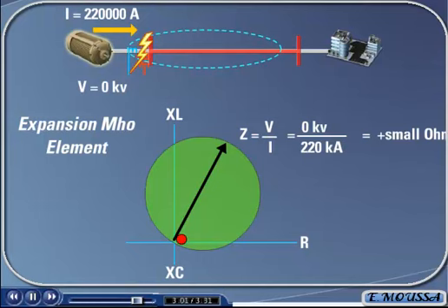To make sure that the Mho characteristic does realize this as being an internal fault that needs to be cleared, the relay recognizes the low impedance of the line, sees that the value is positive, and enlarges the radius of the circle. Since the Mho circle now extends past the origin to include a larger area, the location of the fault is sure to fit in the zone of protection. Therefore, the fault can be cleared properly. Notice, however, that the reach of the Mho circle did not change and still extends out to the end of the original zone of protection.